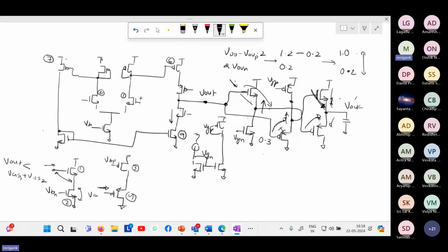So this way you can combine the common drain stage for NMOS and PMOS inputs and then get the final output. The only issue in this case is that the bias current of the NMOS and PMOS common drain stages is well controlled, but the output side common drain stage is not so well controlled. Here the current is going to vary as the signal varies. But from the impedance point of view, it provides lower impedance and good swing also, because for the maximum as well as minimum signal levels, it is able to pass the signal.